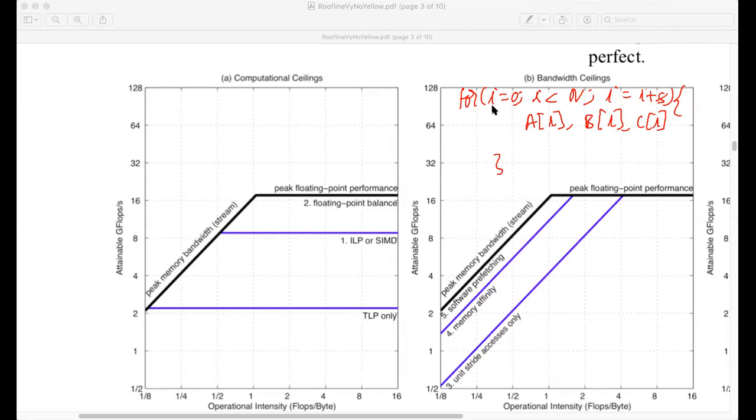Because of that, the net bandwidth that you experience will be way less than the peak memory bandwidth achievable with respect to your program, because you get data and then you discard it. In the last class, Prithvi mentioned that even if he accesses a particular word in the memory, the surrounding 512 bits, the surrounding 64 bytes, are automatically fetched by the DDR controller.